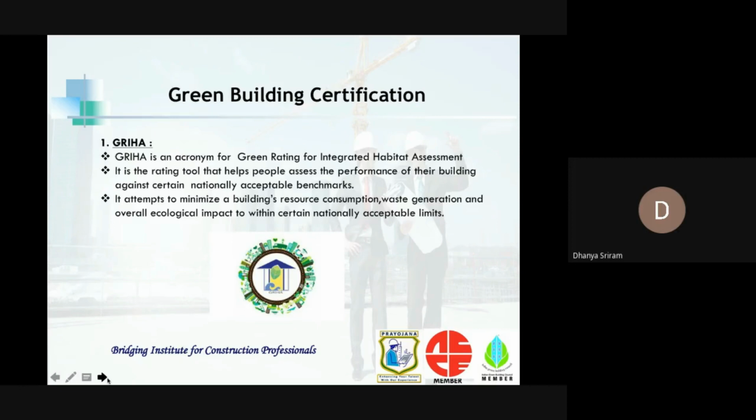The highest points, 6 points each, are given for the criteria: optimize energy performance of the building within specified comfort limits, optimize building design to reduce conventional energy demand, and utilization of fly ash or agricultural waste as recommended by the BIS in the building. There are 36 criteria, each with points. That also includes wastewater treatment, reduction in waste during construction, efficiency of waste segregation, and so on.